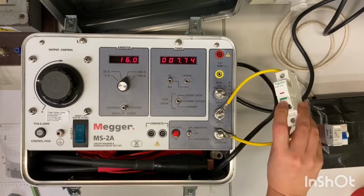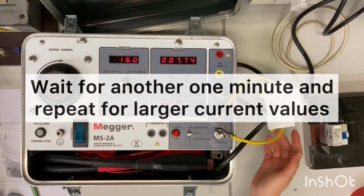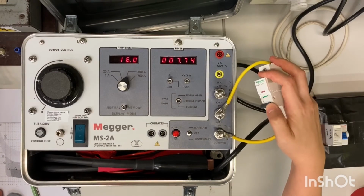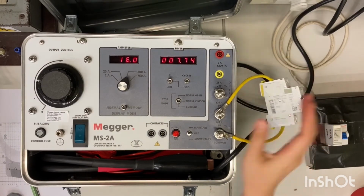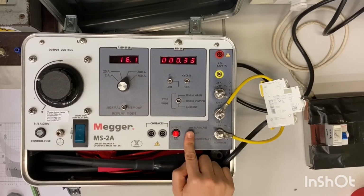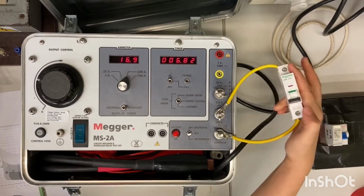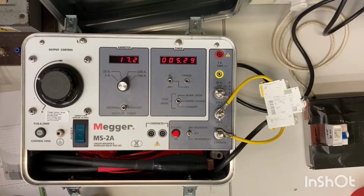For a current of 16 amp, the disconnection time is 7.74 seconds. And we repeat the procedures for other larger current values until the MCB trips instantaneously. That is, the disconnection time is less than 0.1 second.